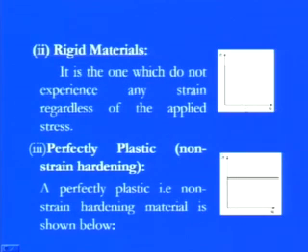That means whatever the surroundings are, there is no change of the shape of the material irrespective of the load application or the stress applications. So here this curve will simply be blank, because nothing will happen even if we apply the load, in terms of the stresses or the strain. So it is a blank. Rigid materials exhibit zero result irrespective of the stress and strain, so we cannot set up any relationship between the stress and strain in this kind of material.